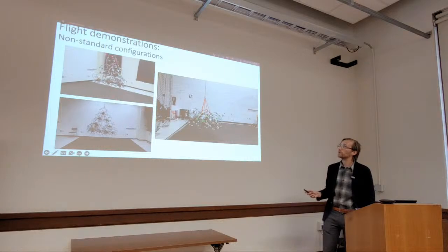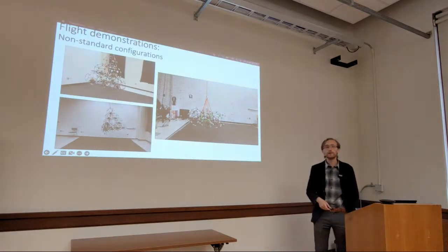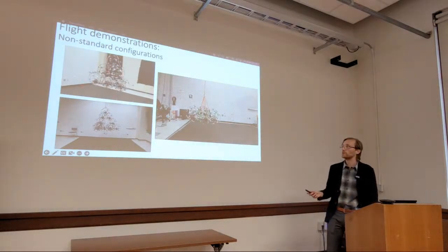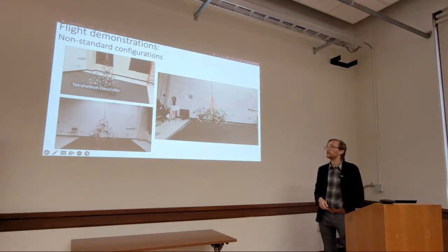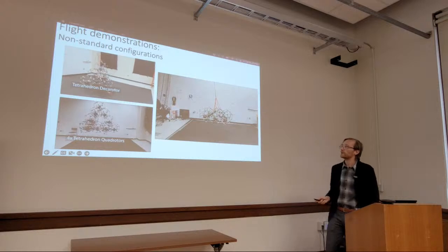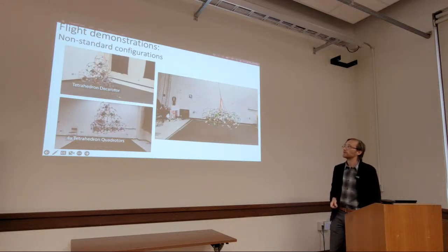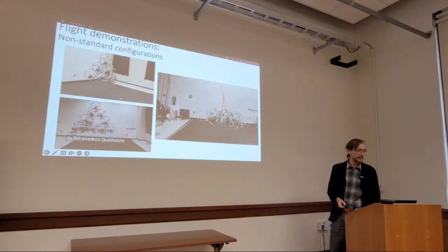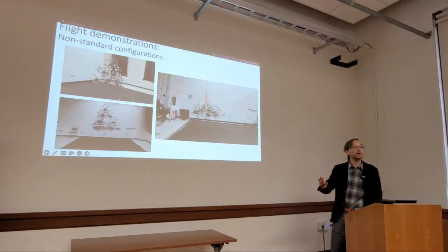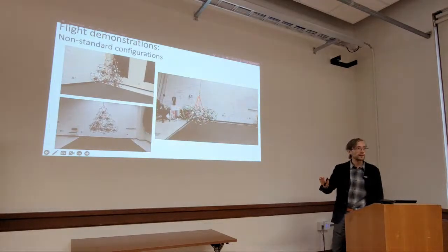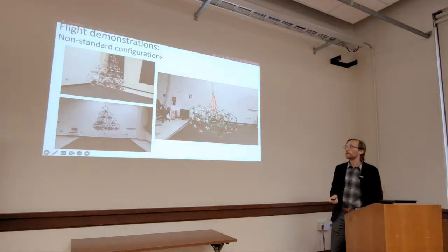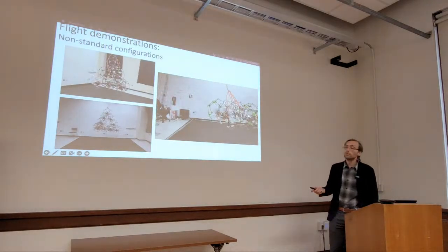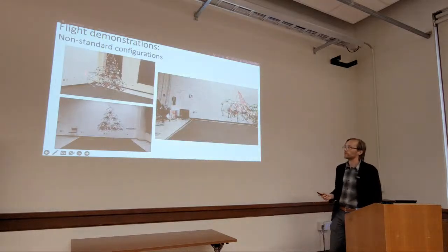For the tetrahedron configuration, the main issue is that there is some wake interaction with this module shape, and so it makes it more challenging to stabilize. We used off-the-shelf flight controllers for that, and the overall tuning has to be done manually, which was a very challenging process for these configurations.